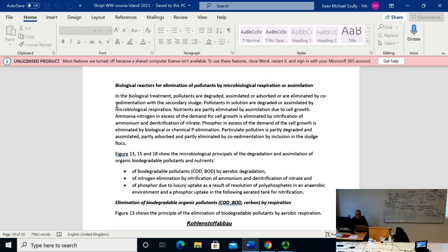And we saw that only 70% of the filterable particulate matter is eliminated in the primary clarifier. So it's 30% for the biological system. And out of those 30%, only a certain fraction is biodegradable. And what's non-biodegradable, you will not find in the effluent. Where are they?